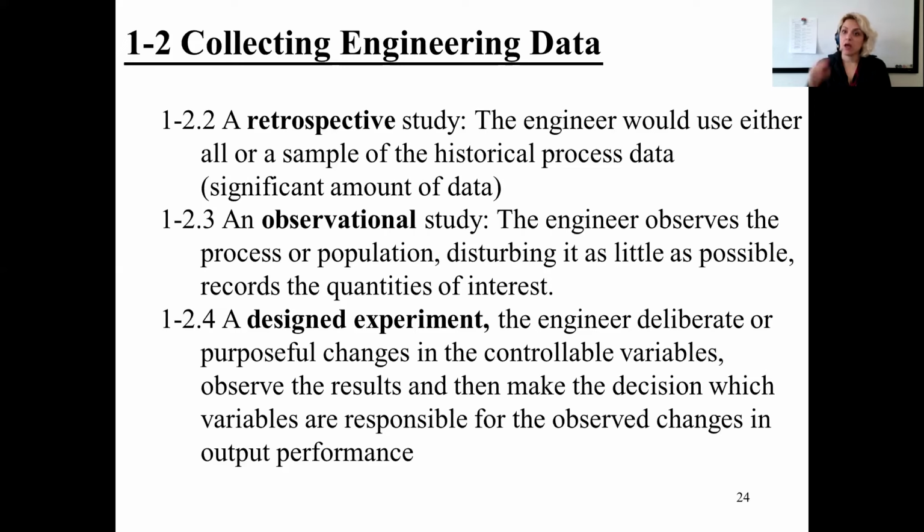For example, I'm recording the temperature, and I'm going to change the pressure of my column to see the effect on the temperature, right? When I'm recording the data, that's designed experiments. It's different than the historical and the observational one. The one thing that's important to learn in designed experiments is to know which variables you're changing, it's important, right?